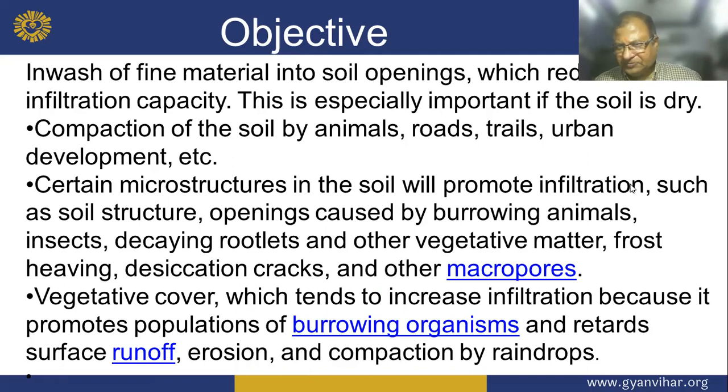So openings caused by boring animals, insects, rotted roots and other vegetable matter, cracks, and other macroscopic openings promote infiltration, because vegetation promotes the population of boring animals and retains surface runoff.